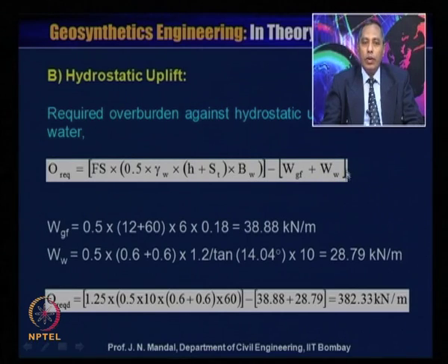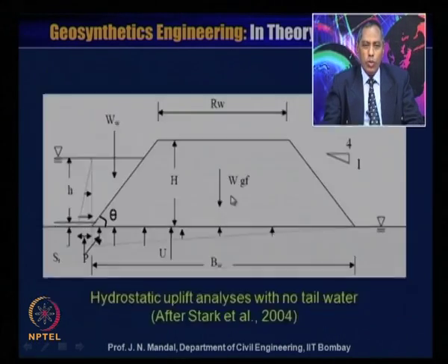Similarly, you have to calculate Ww, that means the weight of the water. This is the weight of the water here, a triangle. This distance is H and this distance is St. This St we have generally considered as 10% of the height H, that means 0.6. So this is St 0.6, and this small h is also given in the problem as 0.6.